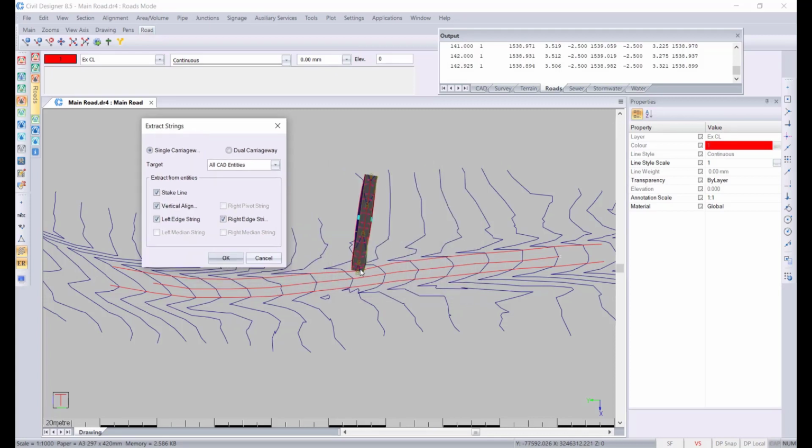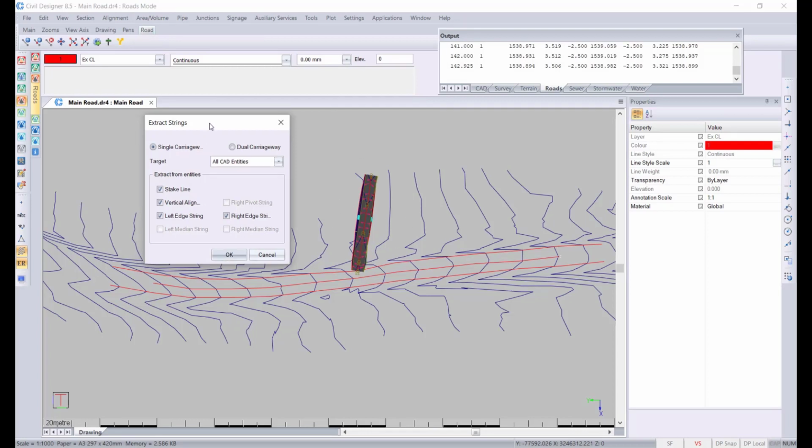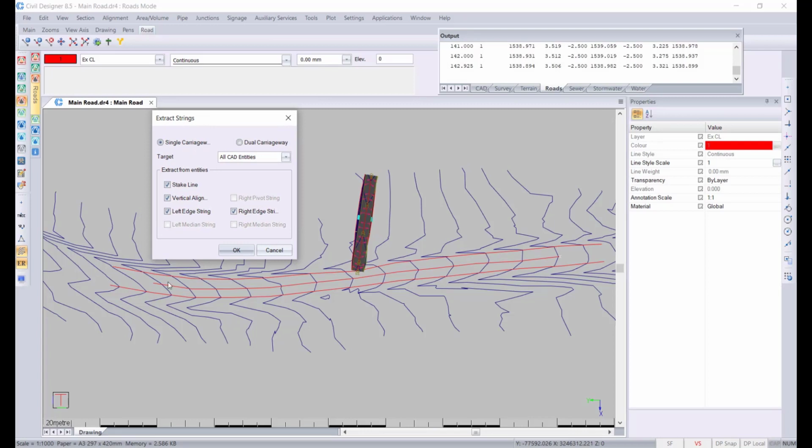Normally, as in the case of this road number here, the minor road, the information is a string road, but it is being modeled off the tabular. So your alignment, horizontal edit, vertical edit, and your edge controls is where the information is stored, and it is displaying that information in the strings. With this one, the information is stored directly in the strings itself. So that comes in very important later on when we do road widening.